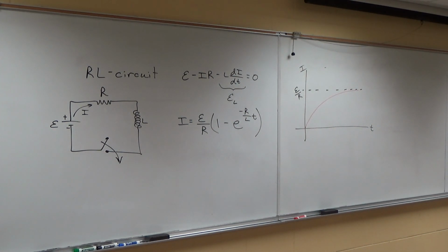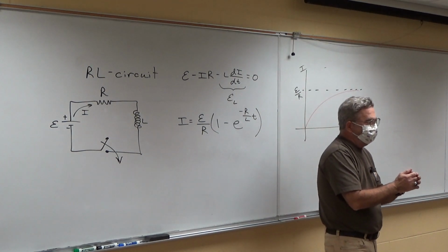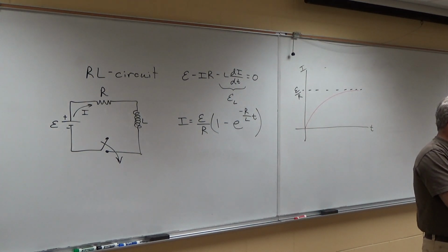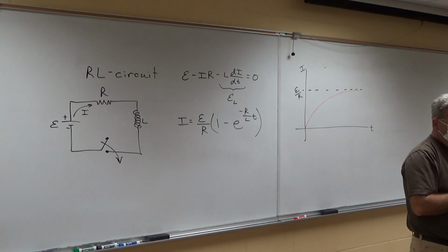Have you ever been running a vacuum cleaner or a motor and you unplug it and you see the spark jump from the receptacle to the little plug? Sometimes you see it when you plug it in, but oftentimes it's running when you unplug it. That's what's happening. You have an inductive load and you have energy stored in the magnetic field due to the current, and as soon as you turn off that current, that energy has to go somewhere.